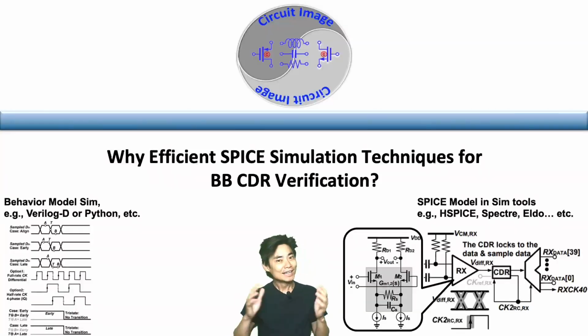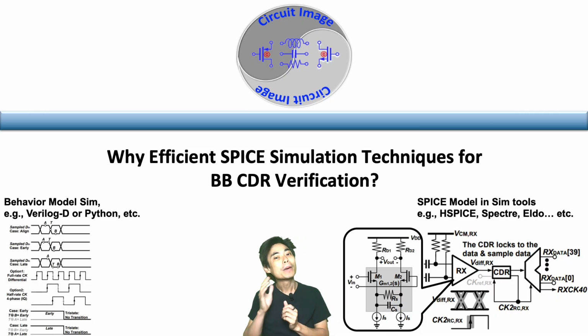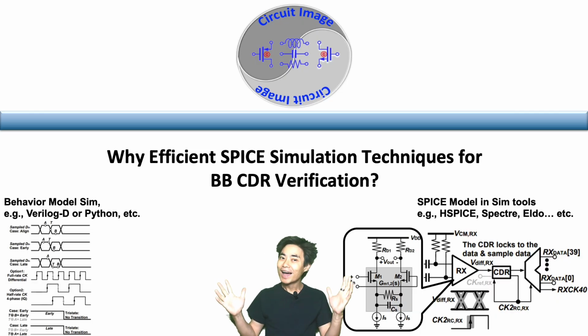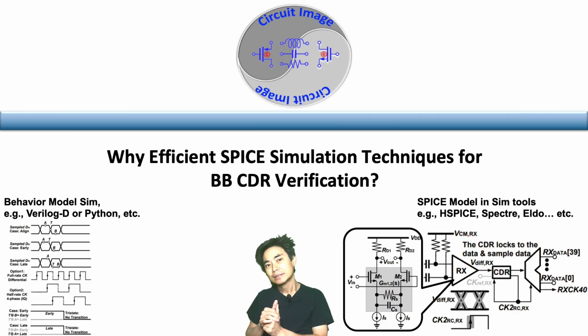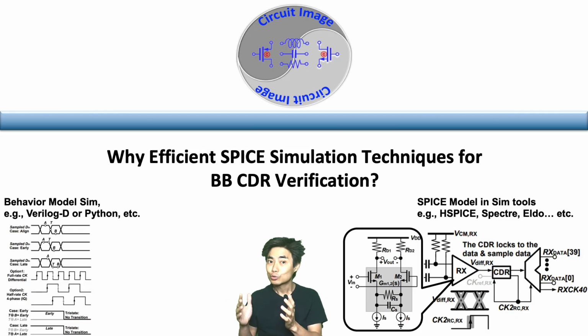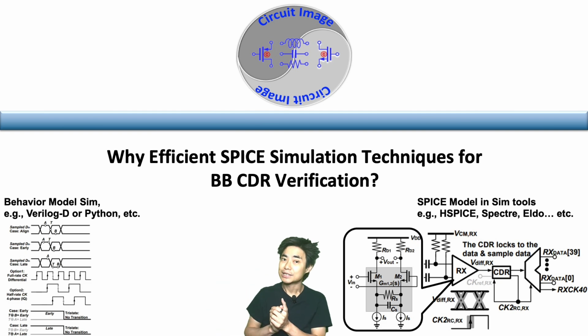Hello, let's begin with a question. Why do we care about efficient SPICE simulations for bang-bang CDR verification? On the left, we have behavioral simulations using Verilog, Python, or MATLAB. They are fast, intuitive, and great for tracking algorithms over bang-bang PD logic. These models are quick to evaluate early and late sampling decisions.